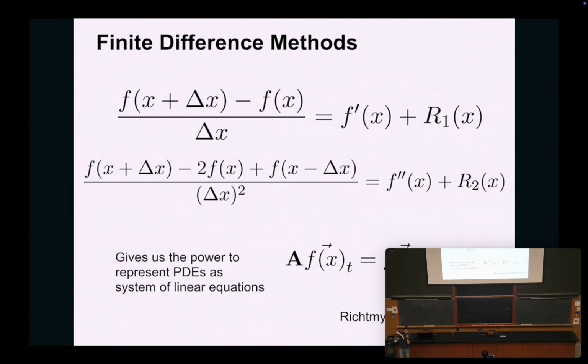We want to capture the curves because that's where it matters to get the most detail. If density increases rapidly, we want to capture that curve. If I had grid cells that are really spread out, I'm not going to capture that change in density really well. Okay, so it's the change in density versus the density. Yeah. If I have high density but it's not changing much, I don't care if my grid size is really big. It's almost the same.